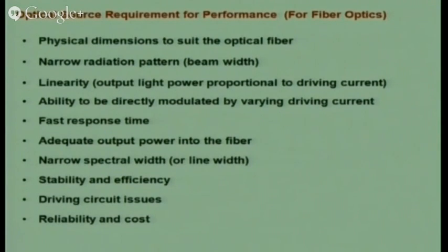The radiation pattern matters because the fiber core diameter is of the order of 8 to 10 micron for single mode, or 60 to 62 micron for multi-mode. So the emission pattern of the source should match the dimension of the optical fiber. That means it should be a narrow radiation pattern. There should also be linearity: when I supply current, the output should be linear, so as to avoid nonlinear phenomena.